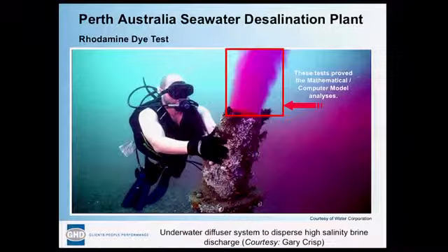What is the other side of this technology? Well, one part of it is that you make a brine, right? You get a very saline wastewater to be disposed of. That saline water contains typically twice the salt of source seawater, if you're doing seawater desalination. As a result, you worry that when it's put back in the ocean, you'll produce regions of locally high salt concentration, which would be inimical to things that live there.